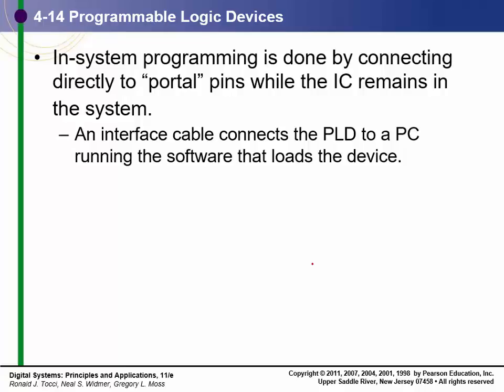In the lab, you don't want to keep throwing parts away, so you use the reprogrammable. But when you go into production, you want to use the OTPs because they're cheaper. They're also faster, smaller, and use less power. One-time programmables have a lot of advantages in the production unit, but in a design lab, they get expensive and you keep throwing them away.